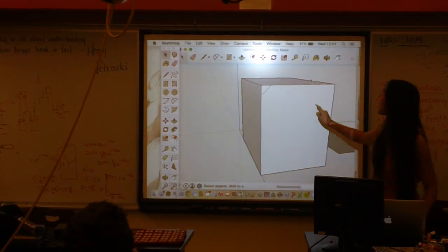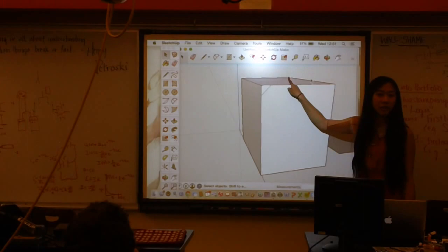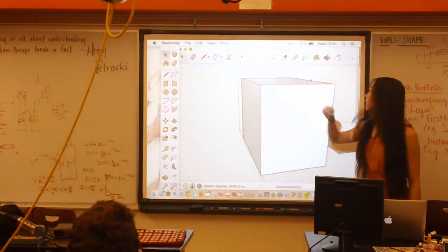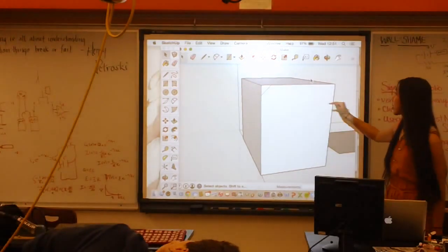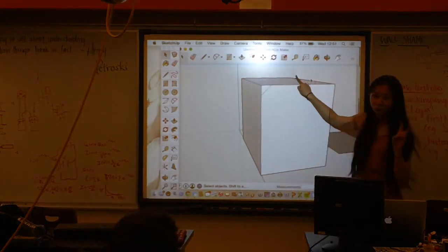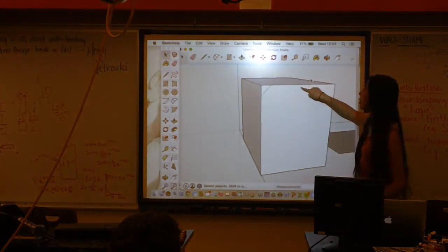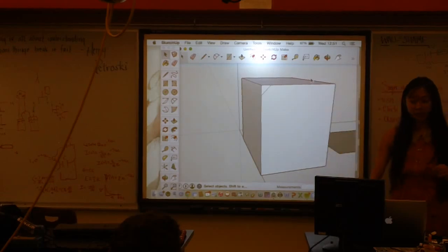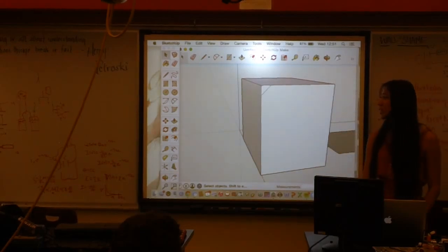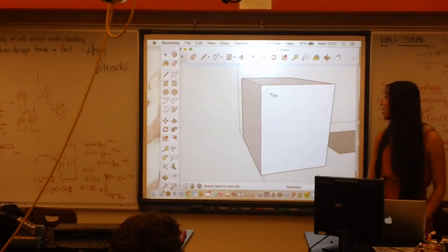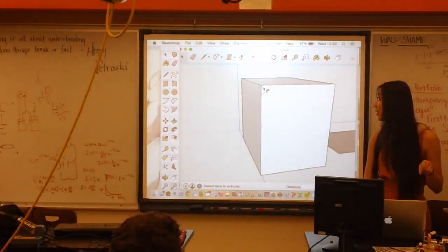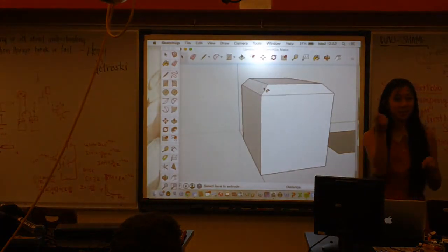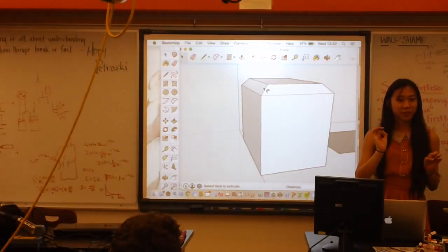To select the top surface of this prism. So what I've just done is I've designated the edge of this entire prism as my thing to follow. And now I'll select the Follow Me tool, and then I'll select the triangle shape as the shape that is doing the following. And you can see it cuts all around like that.